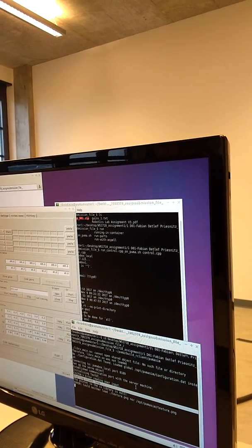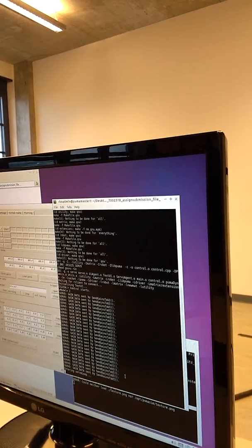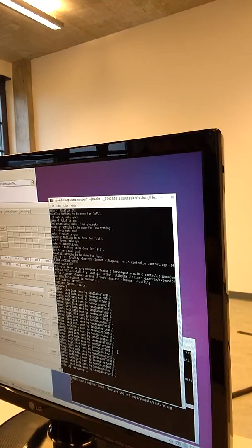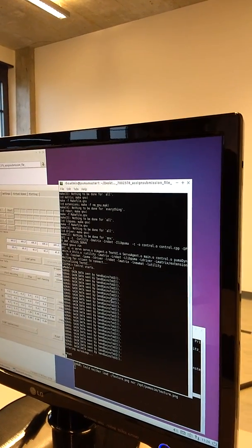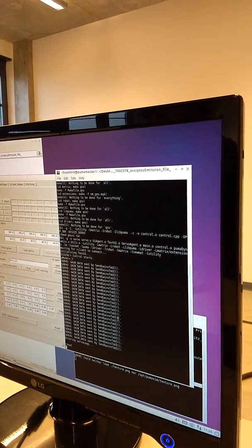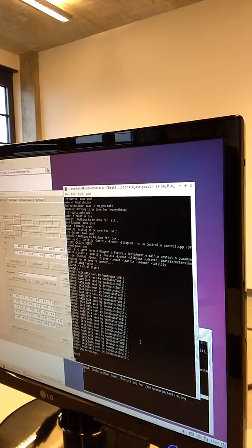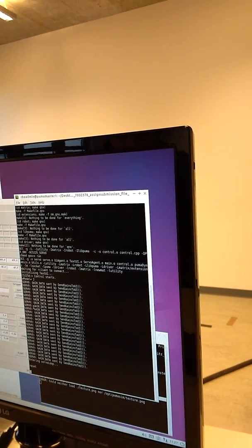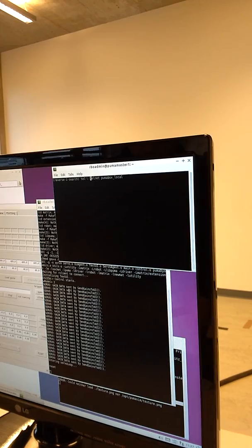Now, reset. If you move the robot while it was turned off, or maybe actually the first time you do this in the morning, you should do a reset, which it's not doing right now. Okay, so sometimes you get kind of a command prompt in that thing, and then you can just type reset, and this will set the current configuration of the robot to 0, and it helps to sync that what's shown here in the PUMA sim and what's shown on the real thing is the same thing. If you don't get that prompt, just log in via telnet, start the thing manually, and then you get the prompt definitely. So we can also demo that.